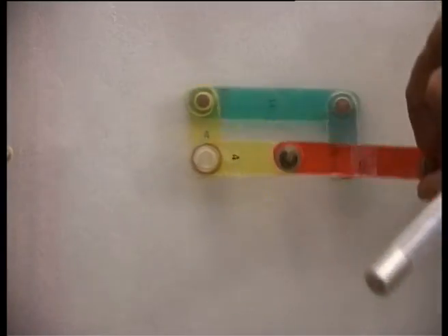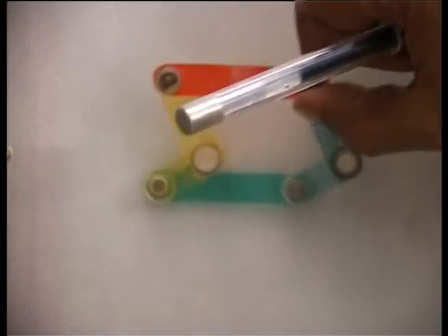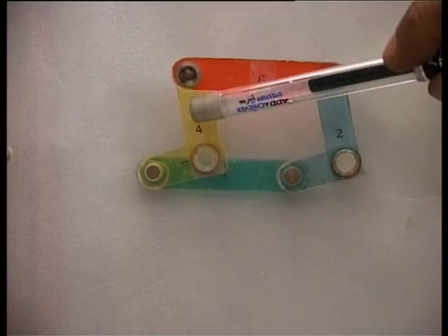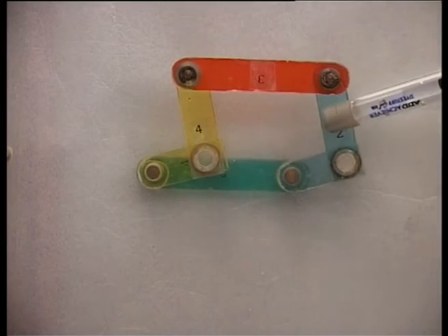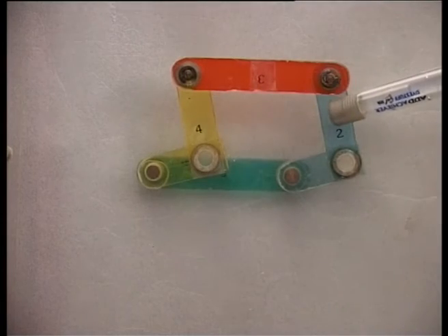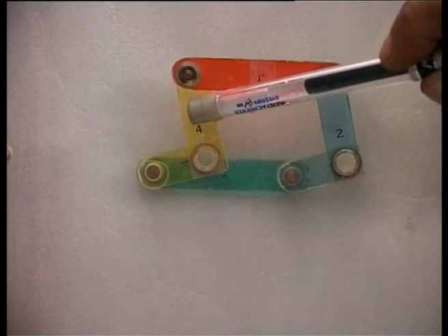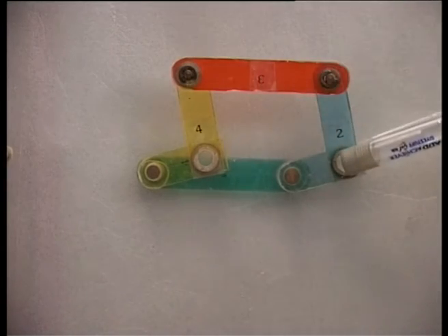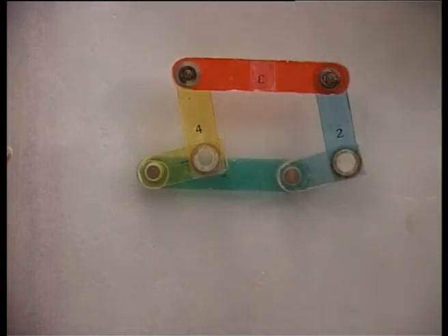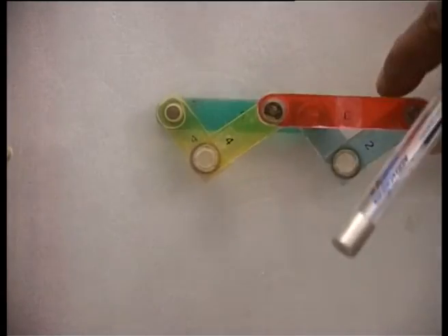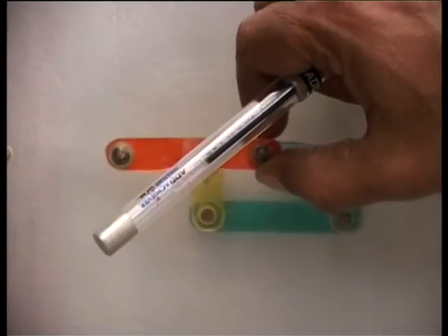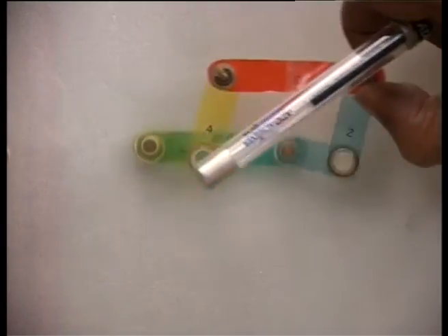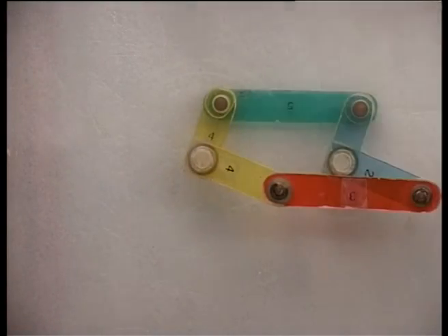The parallelogram linkage is very useful because it maintains unit angular velocity ratio. This crank and the follower are always parallel. So, it transmits unit angular velocity ratio from the input to the output link. But to ensure that it remains a parallelogram and does not flip back to the anti-parallelogram configuration at the uncertainty configuration, we must have this extra or redundant coupler, this one.